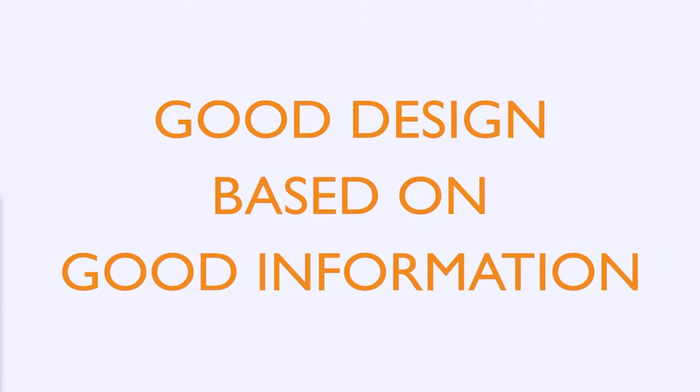So we've seen throughout today's presentation that the most important factor in detailing with contaminated sites is good design based on good and accurate information. Whether it's conducting a thorough investigation into the historical uses of the site or ensuring the correct membrane for the job is well installed by contractors, a good understanding of the risk factors involved and a well-developed holistic remediation strategy is key to achieving a safe and good value solution.